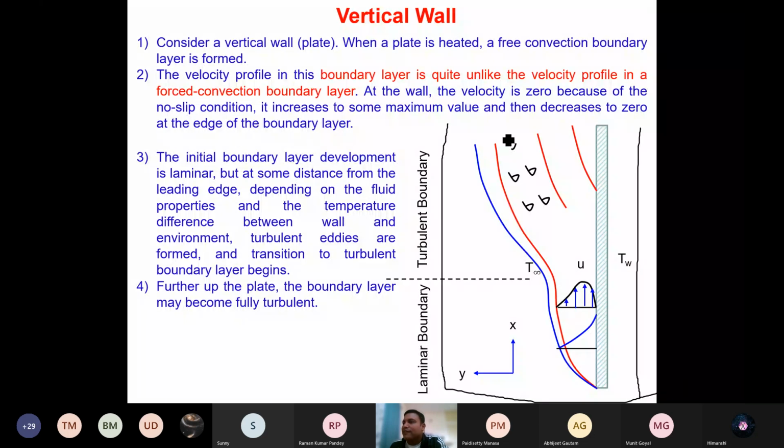So that's why the boundary layer thickness increases, because the amount of heat added increases as you move from this end to this end. And the movement is taking place in the upward direction because the buoyancy force is going to work in the upward direction, isn't it? So you get this type of boundary layer because the buoyancy force acts only in the upward direction. That is the only reason. Otherwise, we shouldn't have got this type of boundary layer. Did I answer your question?